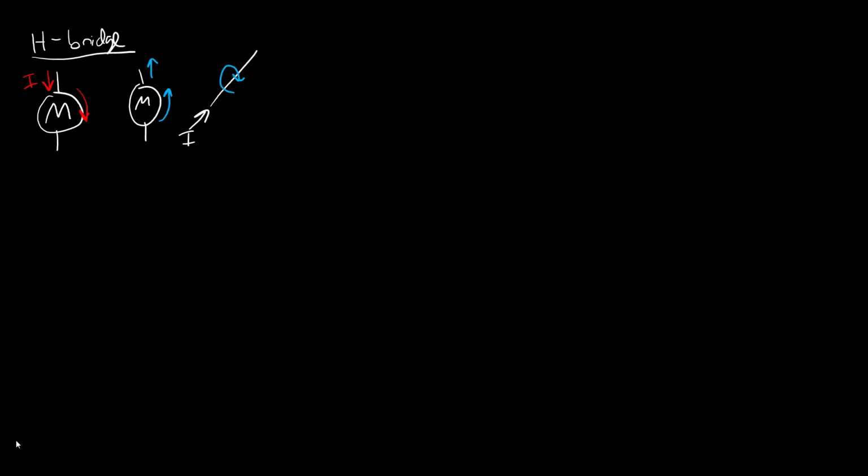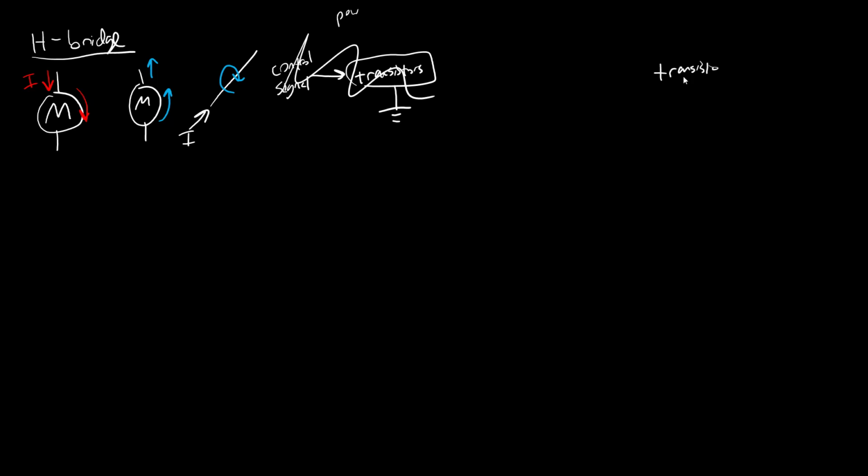In the previous couple of videos in this series, we talked about both BJTs and MOSFETs, two different types of transistors, where we had this basic configuration: you tied one pin of the transistor to ground, you sent a low power control signal from a microcontroller into one pin of the transistor, and you had some high power load that you were controlling current through with the transistor.